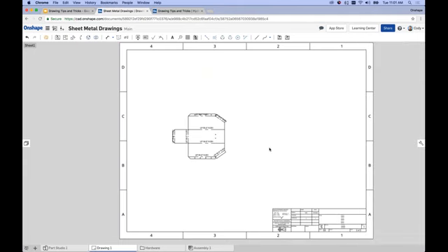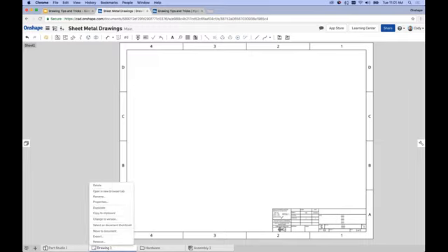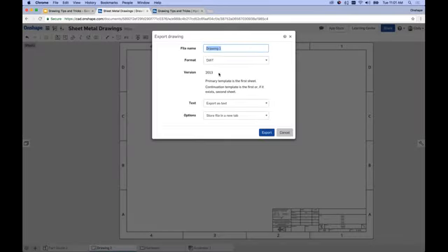I want to build my own template. How do I take this default template that I've built with all the line thickness, the linked properties, and so on? How do I take that and make it a template that I can reuse? And the short answer is right-click the drawing, choose Export, choose Format as DWT, and then the option to store the file in a new tab.